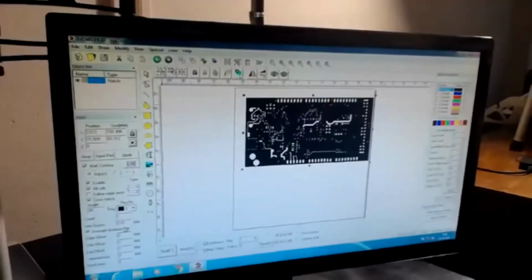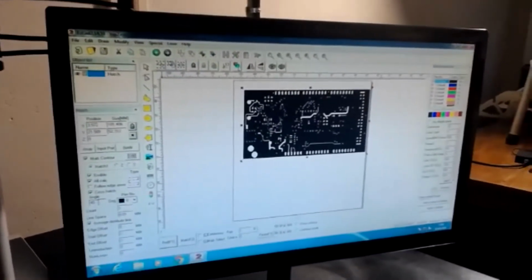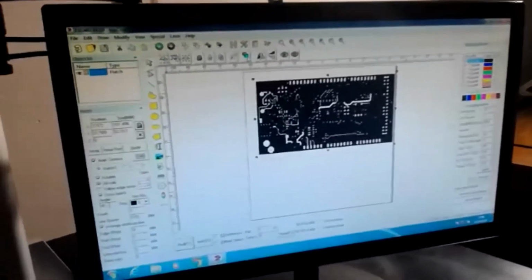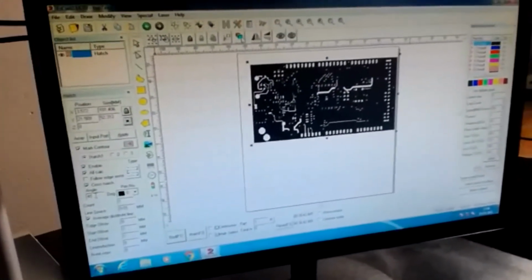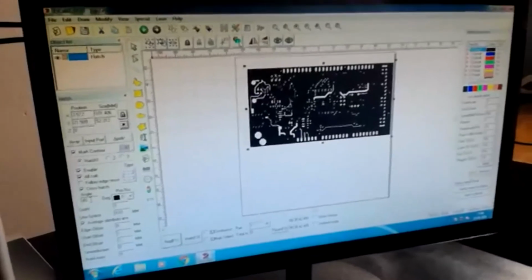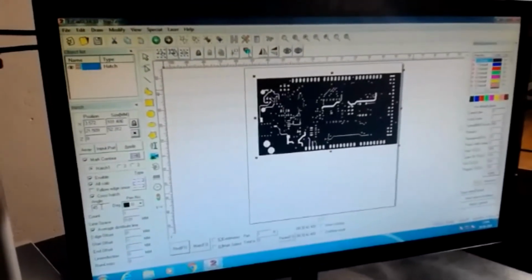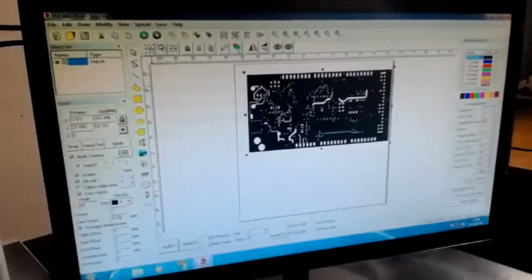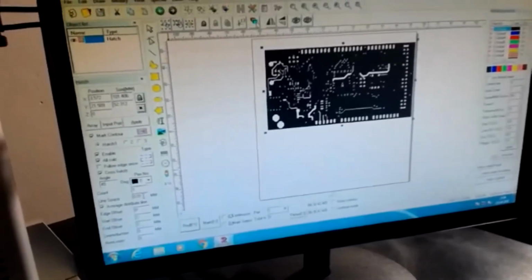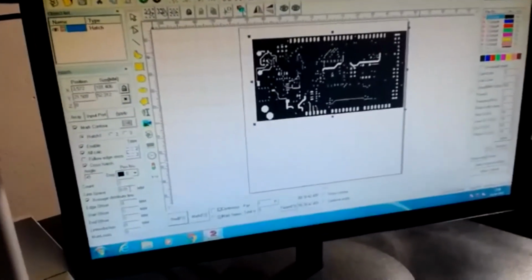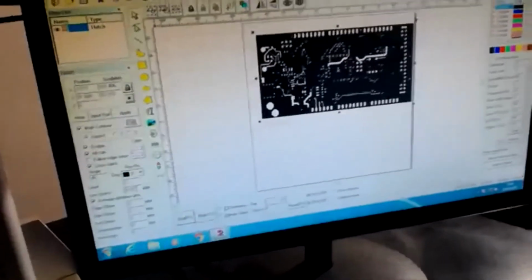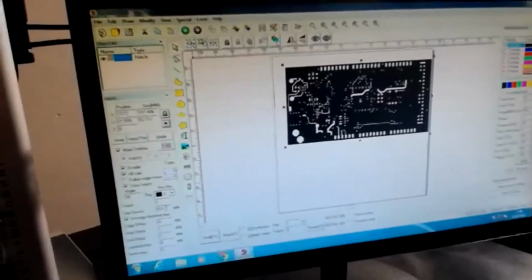So in this, on the left side I have this 45-degree cross hatch. So the etching will be done in a cross format, like a 45-degree angle. It will go from left to right as well as from right to left, because I gave the follower, and also I gave the line spacing of 0.01 mm. So linearly it can be said to be up to 10 microns. Each spacing it will go for measurement is up to 10 microns.